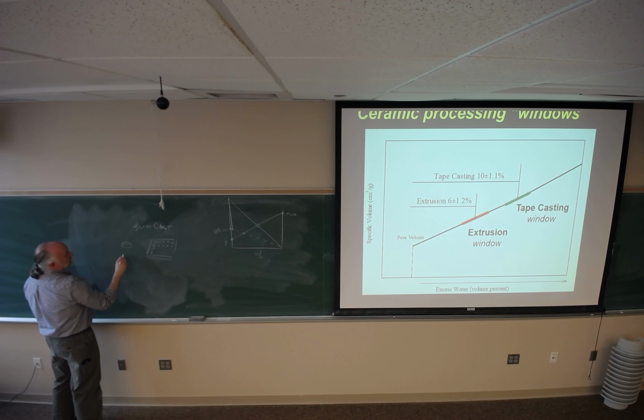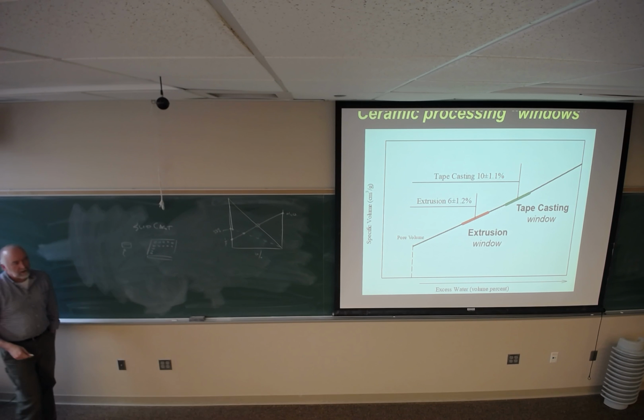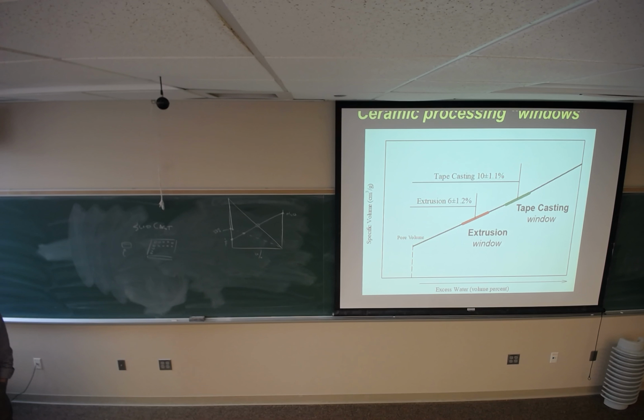It's roughly about a half inch in diameter, and roughly a quarter inch tall. Now, there are two things you can do at this point. You can do what we've historically done: dry that sample, and then measure its volume and density through an immersion method using kerosene. We'll teach you how to do it, but not this week. We figured out a slick way of doing this.